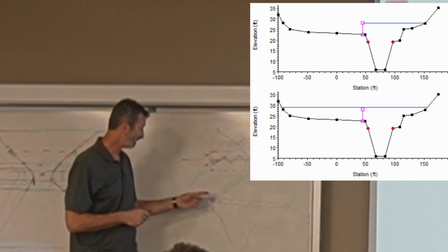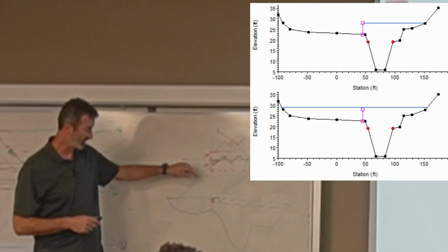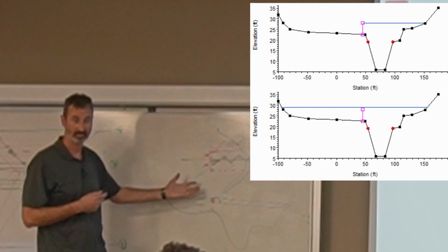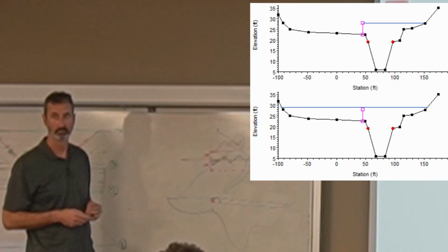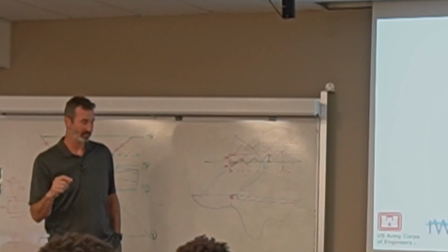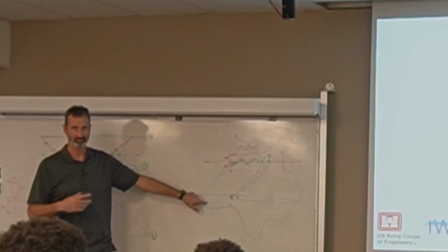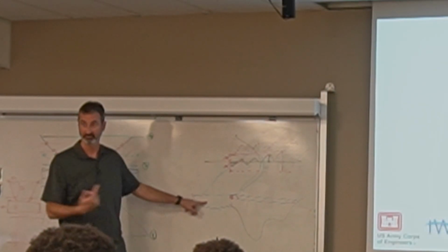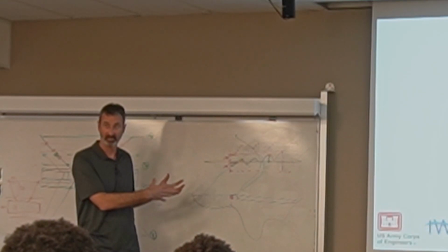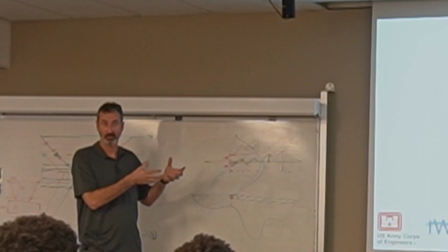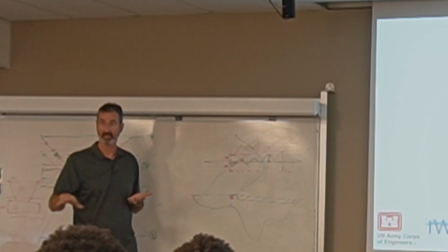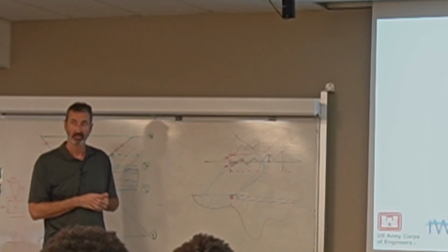If it truly is going over there, there's an issue about how much volume goes over there. Does this thing fill up instantaneously? Well, probably not. So then you could model this as an unsteady model. Unsteady how, and how much, depends on whether this is a really big hole or a detention basin that people actually designed to take the top off of a hydrograph. If an area is flooding downstream, what you can do is let the highest flows over to a stilling basin somewhere so that the peak flows don't make it down to the area of concern.